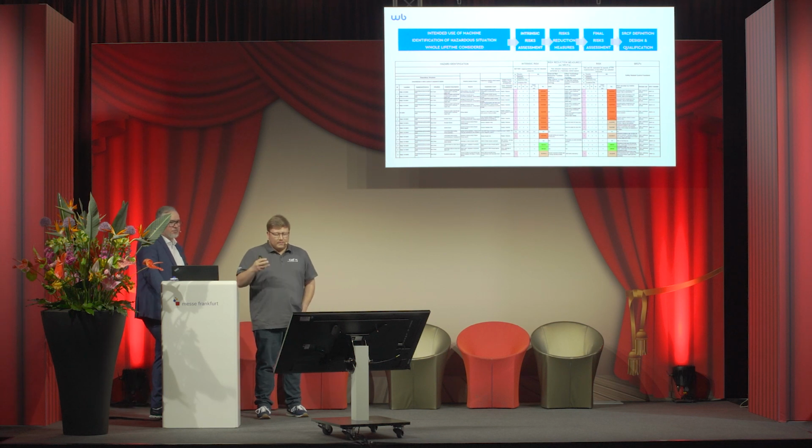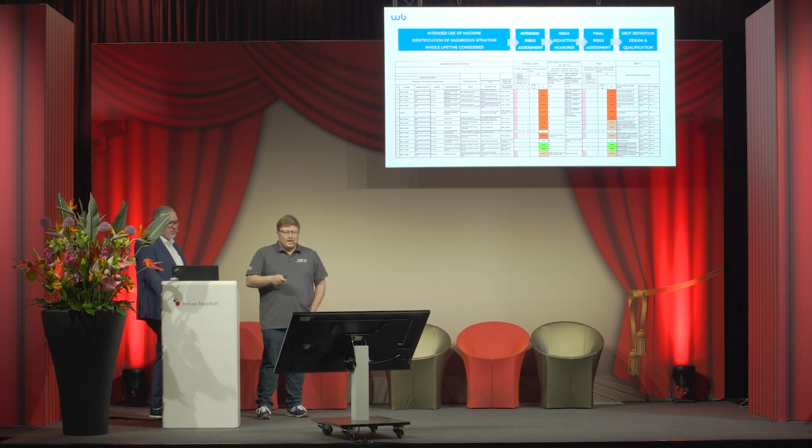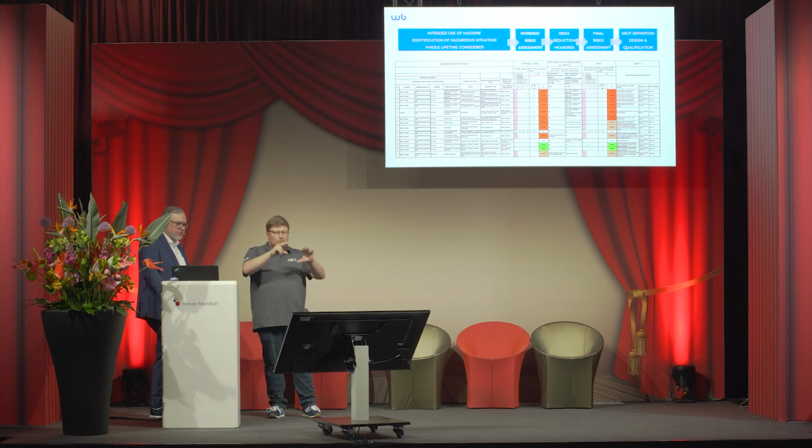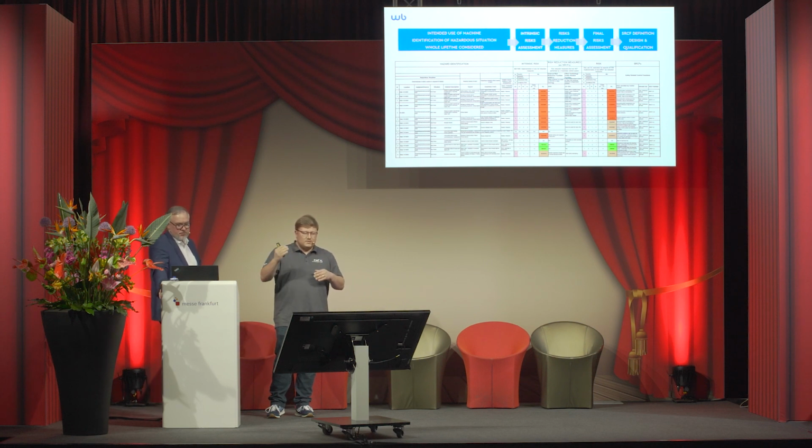Based on what we've estimated as reduction measures, we make another risk assessment. That's the very moment when we are saying, okay, that's the definitive configuration, and with this scenario, we'll have to have SIL 3 or SIL 2, SIL 1, only monitoring, and so on. After that, the last step is to say, okay, I've got my whole overview of my site, of my machines. I know that I need to meet the following requirements, SIL 3, SIL 2, and so on. And I need to say, okay, the control system then needs to provide this kind of safety functions.